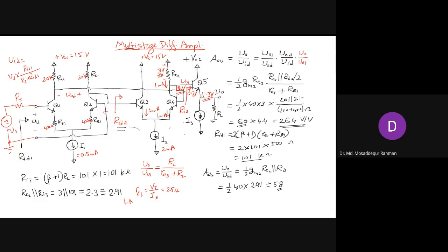So that is in addition to the output voltage V naught. That's a small signal voltage V naught we are considering. And that is a DC voltage, right? And this DC voltage is due to the biasing voltage. In a conventional amplifier, what we do is use a coupling capacitor to block this DC voltage coming to the output or to the load. We use a DC blocking capacitor.